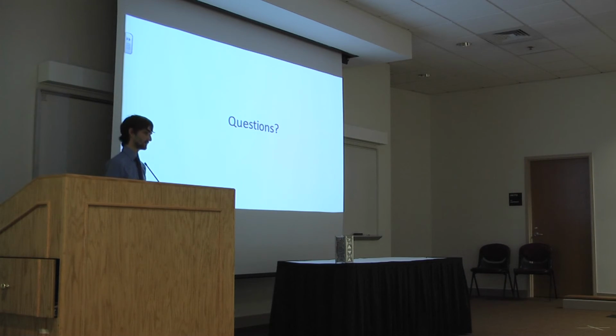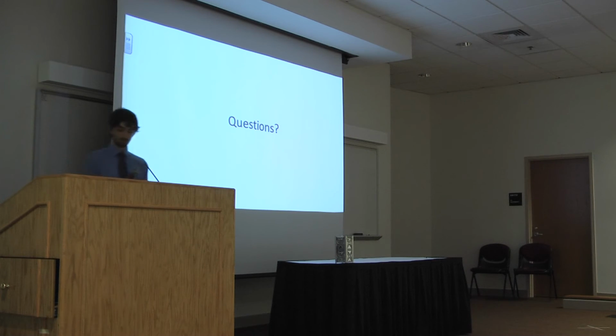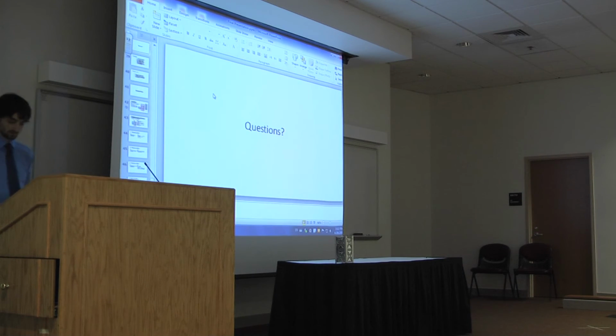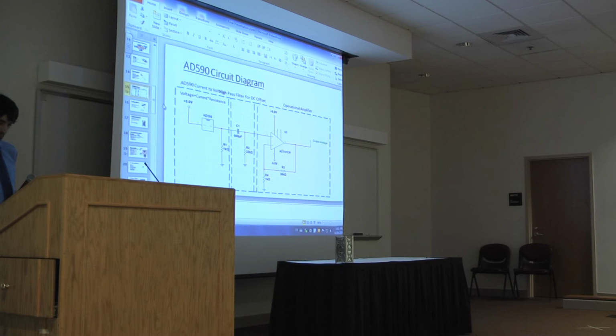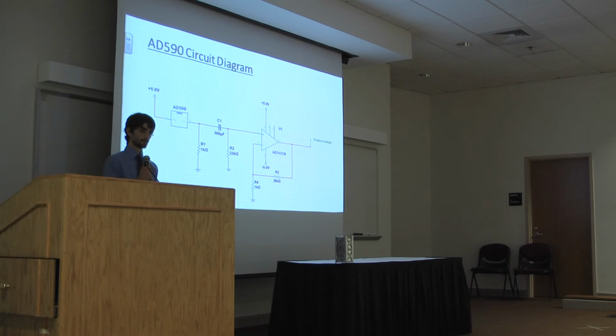All right, questions? Great job. In one of your slides, you showed the signal conditioning, which uses an op amp, which requires a dual power supply, +5 and -5. Where do you intend on getting that -5 volts with a single battery?